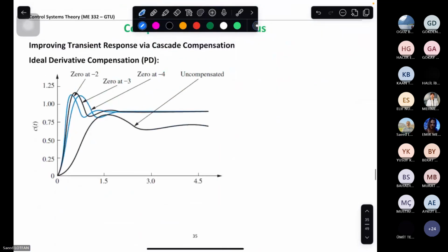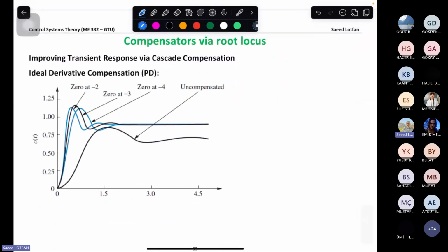No question. And you can see that the steady state error has become better because our input is 1, and the steady state error has become better. So this is input. Steady state error has decreased. And the systems with different zeros can have almost the same overshoot, but they have become faster in terms of T peak has decreased.